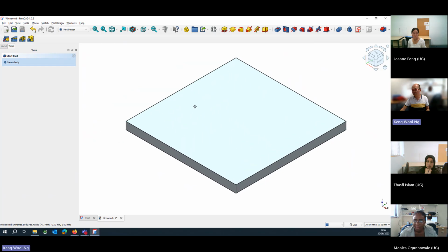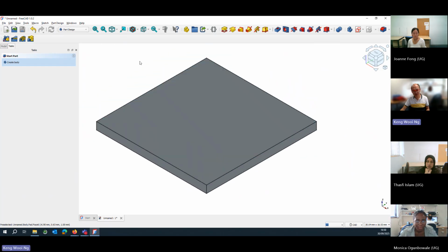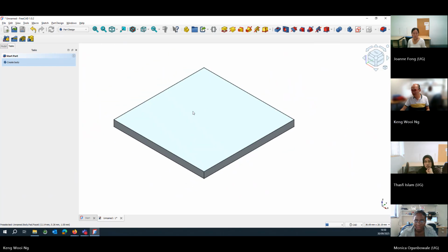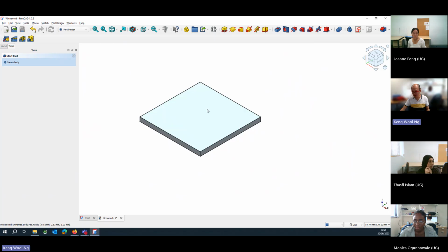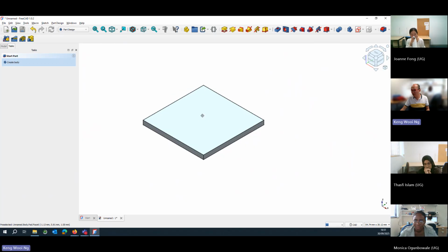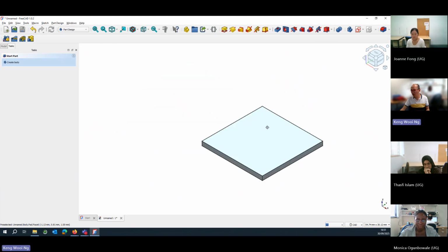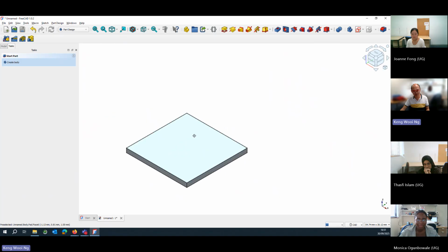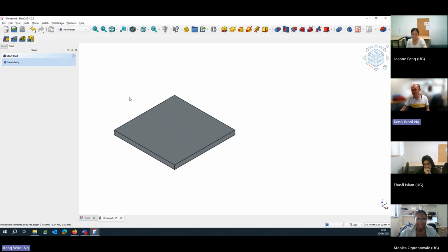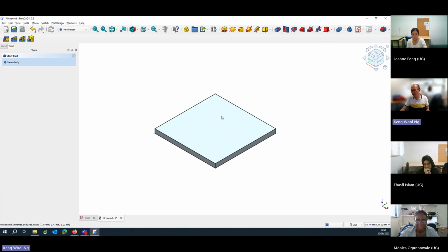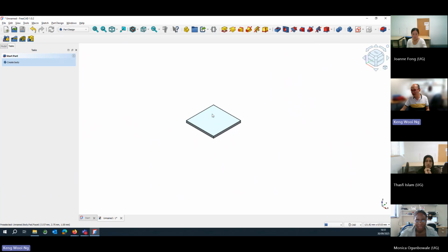Okay, to move your object, you use, okay, I have to try to do this myself and think about what I'm actually doing, because all of this is based on muscle memory now. You press Control and right click on the mouse, hold and drag. Then you'll be able to move the object. To zoom in, use the mouse wheel.